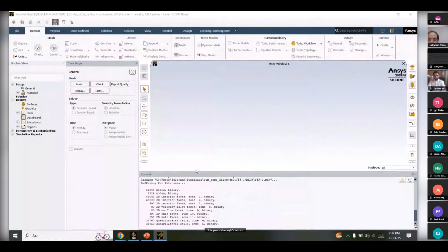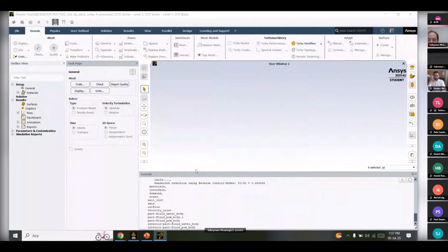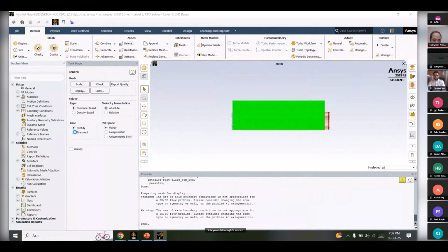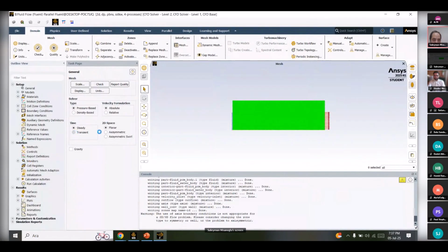We are performing transient analysis. Transient analysis means the values change with time. Here, transient analysis. Also, for axial symmetry, we want to use the integral of the result rather than just a flat representation. Select axial symmetry. Very nice.